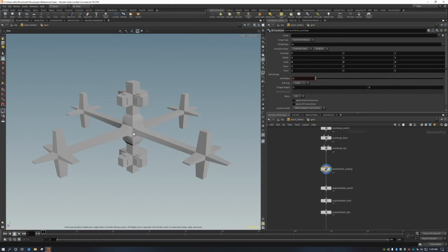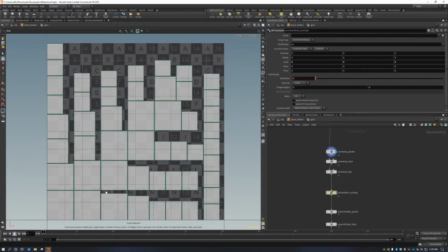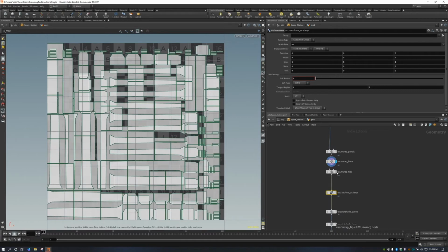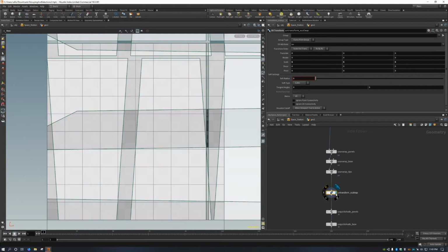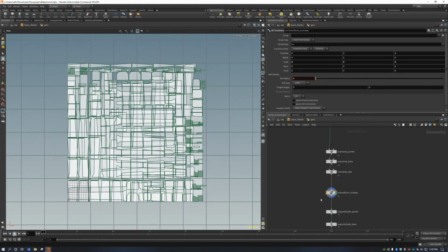If we check out our UV view here, let's zoom back in here. You can see there's 1 layer, there's 2 layers, and there's 3 layers. The reason we're doing 3 separate unwraps like this is because they're going to have 3 separate materials in Unity, and this just uses the UV space a little more efficiently. And then, like I mentioned, we're scaling them up a whole bunch so that the tiling textures will tile more.